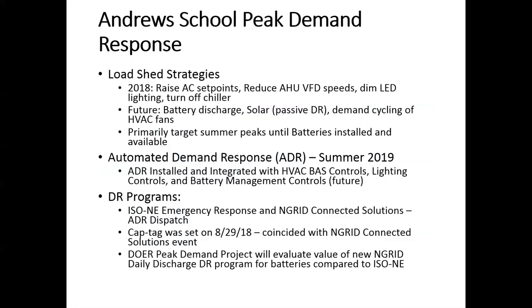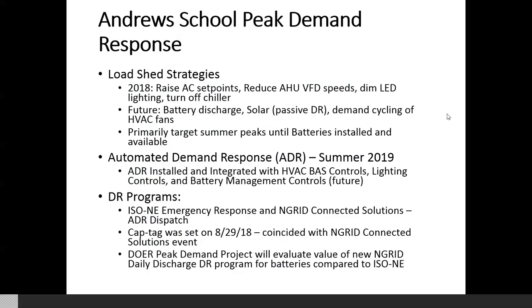One of the techniques that you can do if it's a programmed system is this idea of cycling your HVAC. So you might turn it off for 15 minutes out of every hour and save 25% of the energy. How long you can turn off an HVAC or the fans for it depends on your building, your system, a number of things. I wouldn't just take that number, but it's not minute by minute, but sort of turn it off for a section of time, turn it back on without having too much impact on your occupants.